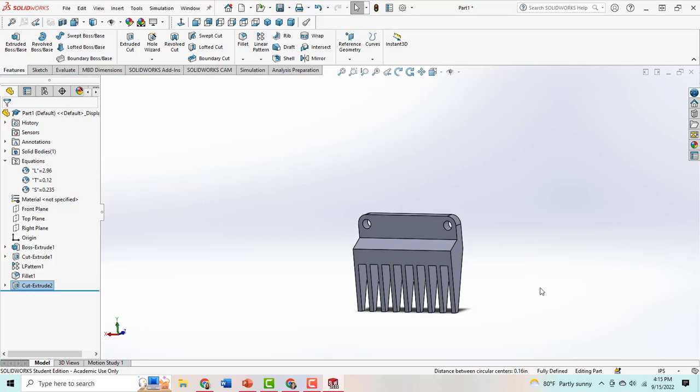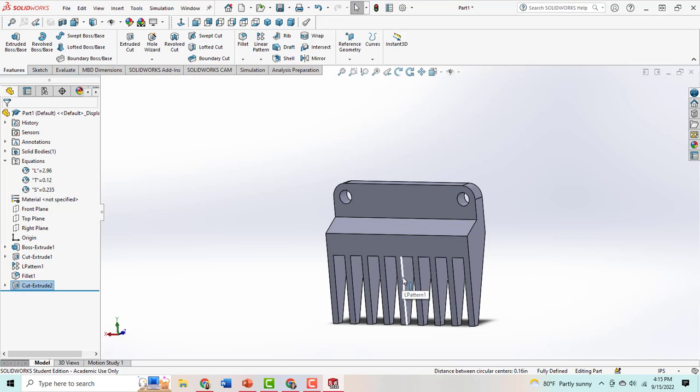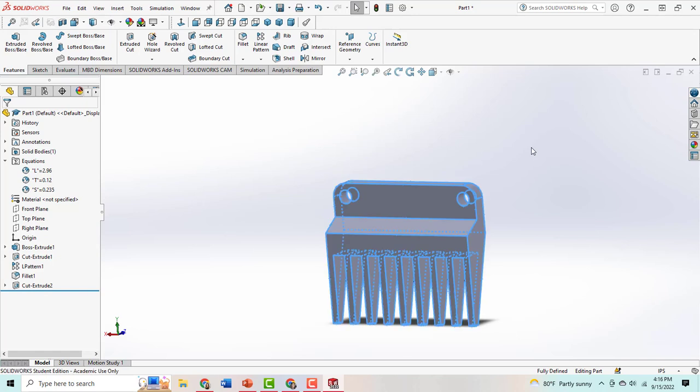So if you look close, you're going to see a note at the bottom of that right face or right profile sketch on your assignment, and it says fillet all edges 0.03. Now it would take an extremely long time to manually click every single edge in this part. So to save yourself time for your fillets, go ahead and hit your Control key and A. Control A will select everything. This works in SOLIDWORKS by selecting all the edges of your part. It also works when you are dealing with any files in a document or folder. You can select all instead of manually control clicking on all of the ones you want.